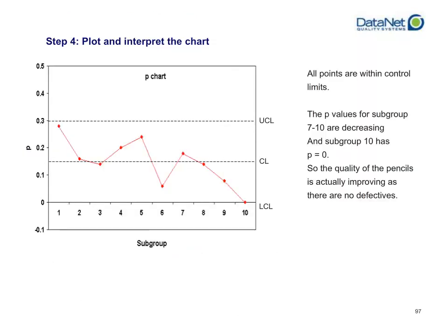Step 4 is going to actually plot the chart. Personally, I like to draw the control limits first, make sure I get my scaling down, then I'm going to go ahead and enter in the individual values for my individual lot numbers for each one of the percentage for each lot number. Once you do this, you can then begin to analyze what you see on the control chart.